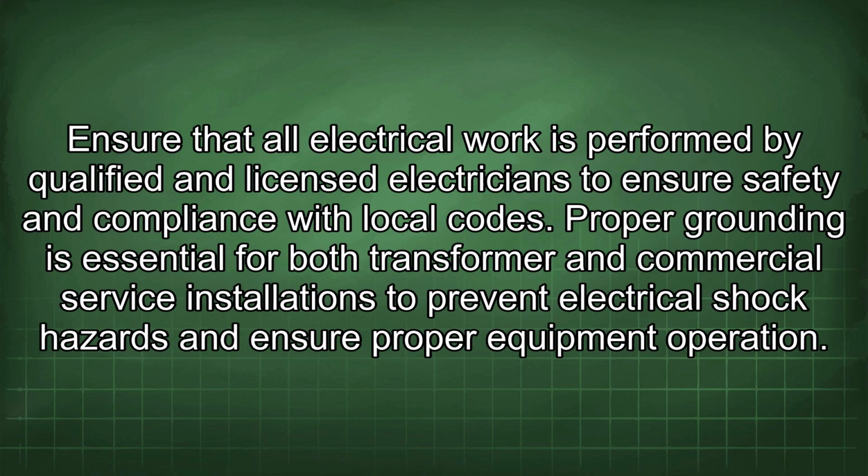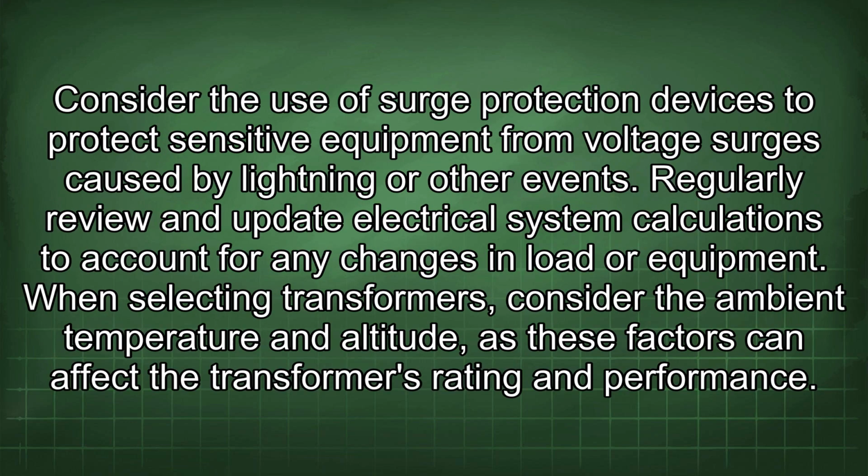Ensure that all electrical work is performed by qualified and licensed electricians to ensure safety and compliance with local codes. Proper grounding is essential for both transformer and commercial service installations to prevent electrical shock hazards and ensure proper equipment operation. Consider the use of surge protection devices to protect sensitive equipment from voltage surges caused by lightning or other events. Regularly review and update electrical system calculations to account for any changes in load or equipment. When selecting transformers, consider the ambient temperature and altitude, as these factors can affect the transformer's rating and performance.